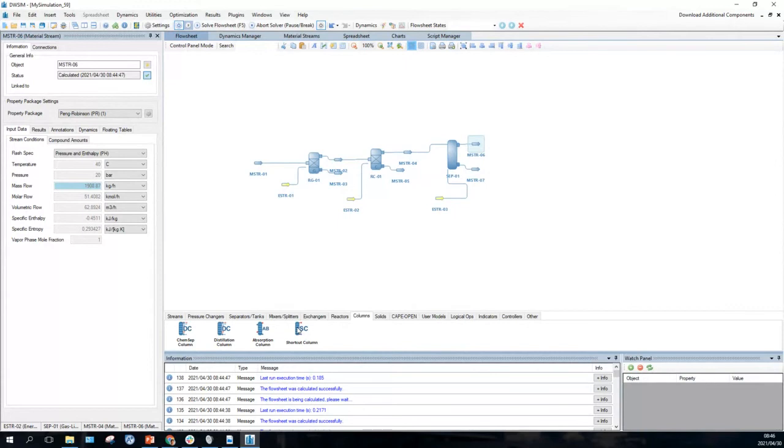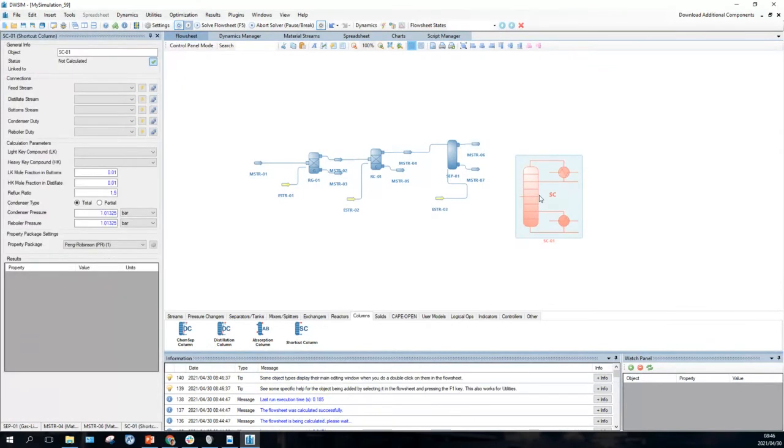And it's got enough options because it does have a partial condenser, which is a really useful option to have, which you don't get on the standard, what do they call it in Aspen? The shortcut column in Aspen doesn't have that option. It's the, what is that? You've learned about it in mass transfer, a shortcut way of doing columns. Anyway, let's put in this shortcut column. It's going to get attached to the liquid line. Just want to move it.